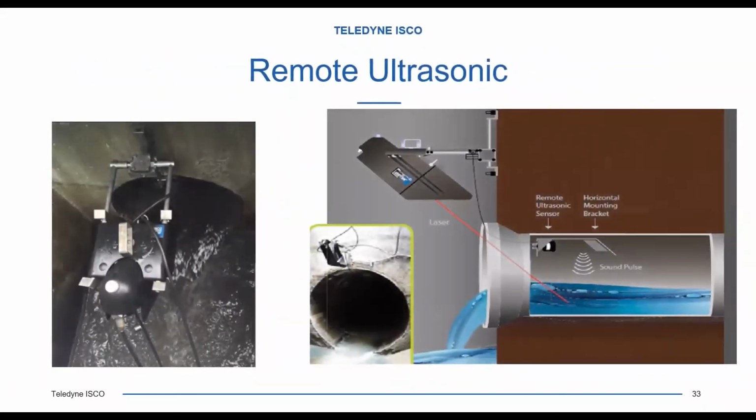All right. So if we don't have good conditions on our pipe, or the water is free falling out, like in the picture here, we were going to have a problem before, because with the initial laser, it was going to read the level right below the sensor. And in this case, you would see it would be dropping out into the channel. That wasn't going to work so well.